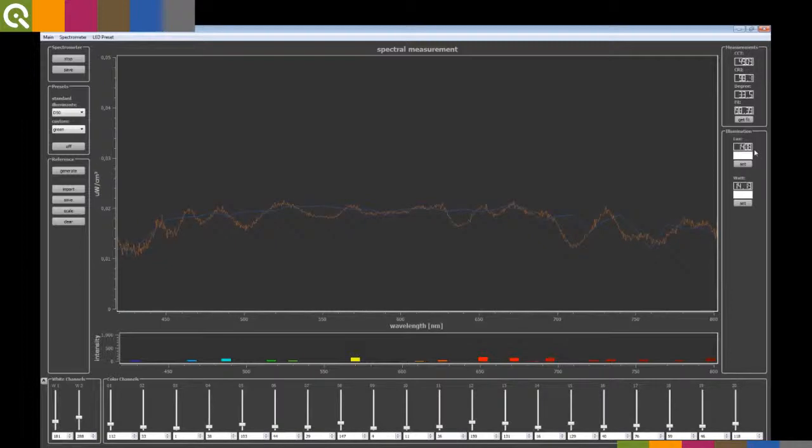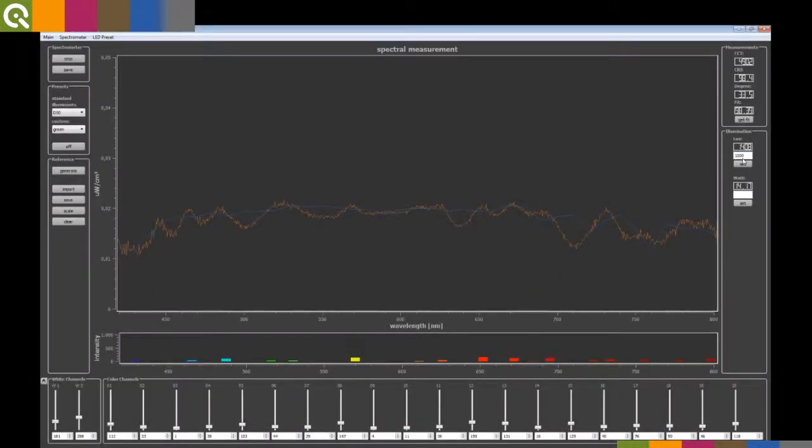Below the measurements, you find the illumination field, where you see the intensity of your actual light in lux for the chart level and the irradiation power in milliwatt per square centimeter. You can increase or decrease the intensity of an illuminant by just typing in a new lux or watt value and pressing Enter or the Set button. The software automatically scales the reference spectrum and then generates the new spectrum.